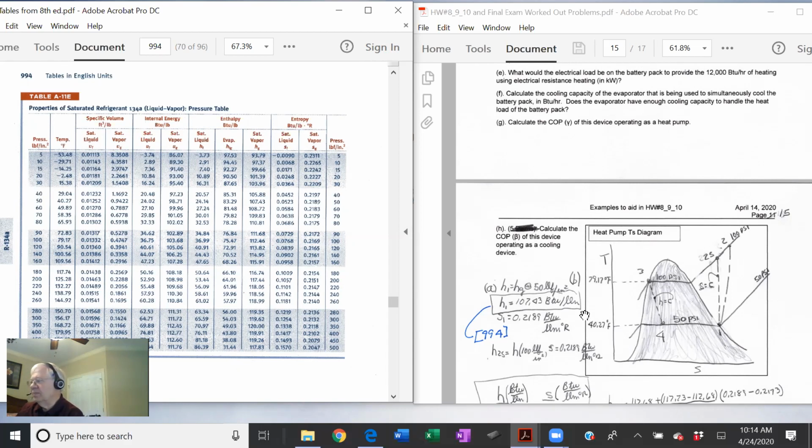Now let's look at the lower temperature. We want to cool the electronics. Well, what kind of lower temperature? If we get the electronics to about 50 degrees Fahrenheit, what is that? That's about 10 degrees C. That's plenty cool for electronics. We don't want to freeze them. So let's look over here. At 50 PSI, we've got about 40 degrees Fahrenheit. That's a nice cool temperature for the electronics. So that's the way we set our pressure. And you don't have to do this design. I've already done it for you, but that's where I got the pressures.